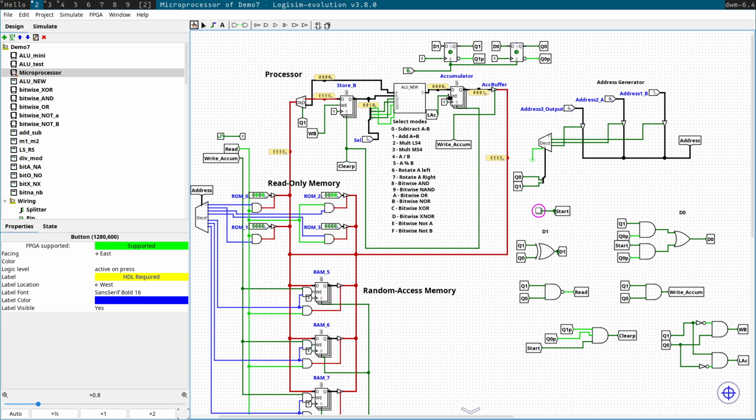And then as we're switching into that mode, we're also enabling the write to this accumulator. And once that calculation has finished, in the second to last state, the accumulator buffer is going to be on along with the write mode to one of these RAMs down here, and we're storing that final output and then returning back to the idle mode right after until we hit start again.